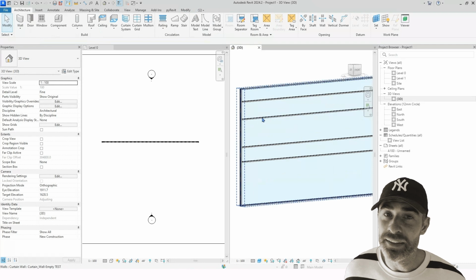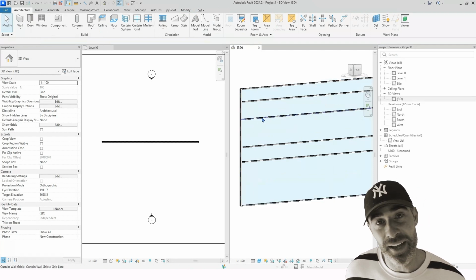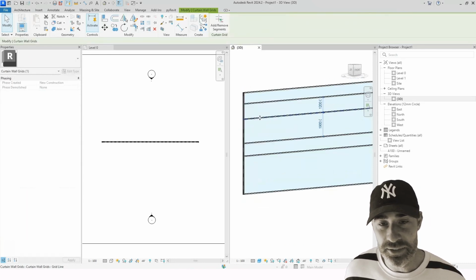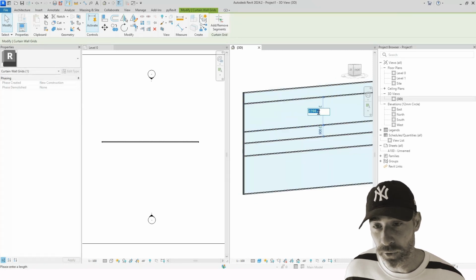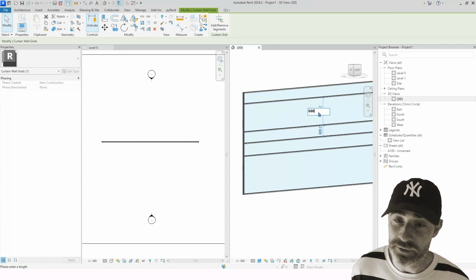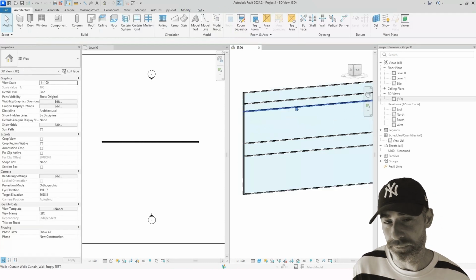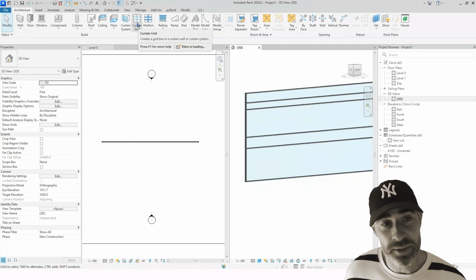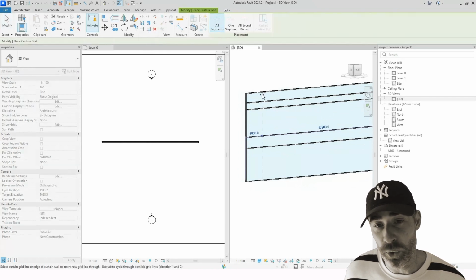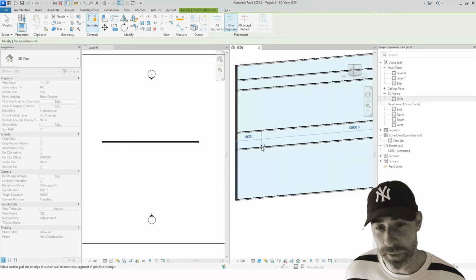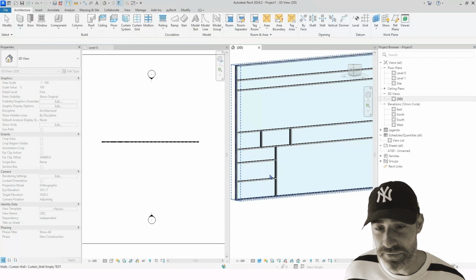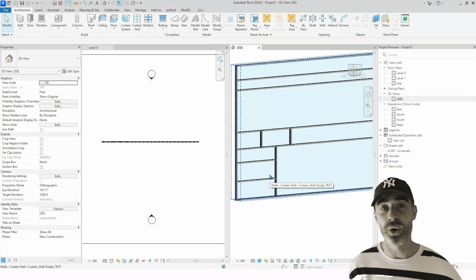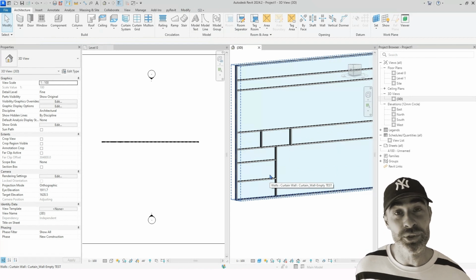These are super easy to navigate, and Tab, again, Tab is going to become your best friend. So as you Tab, hitting on the grid lines, you can change this to whatever, moving, pulling, or coming in here and entering a value of maybe 600 and hitting enter. You can also come to your grid lines, and instead of a whole segment, you can actually do maybe one segment at a time. So maybe there's a custom design that you're going to want to have. You now have that ability to go as custom and as creative as you want.